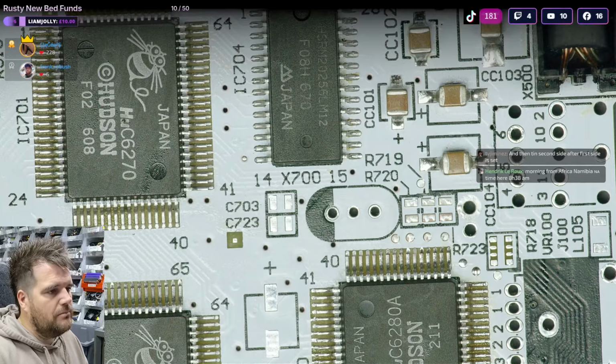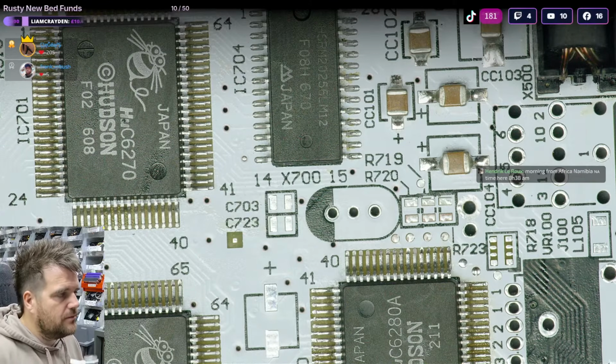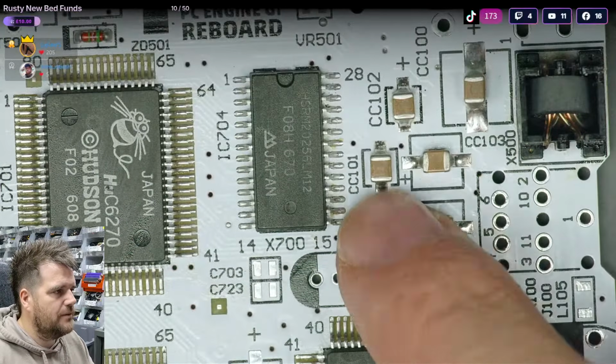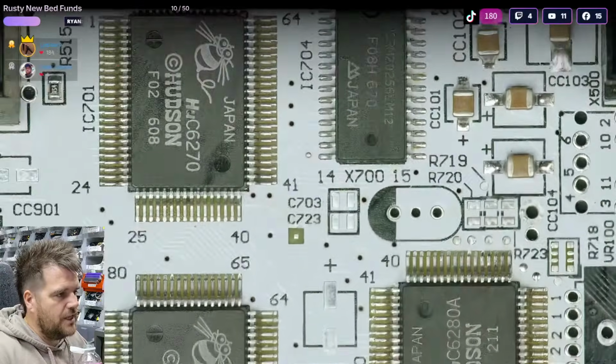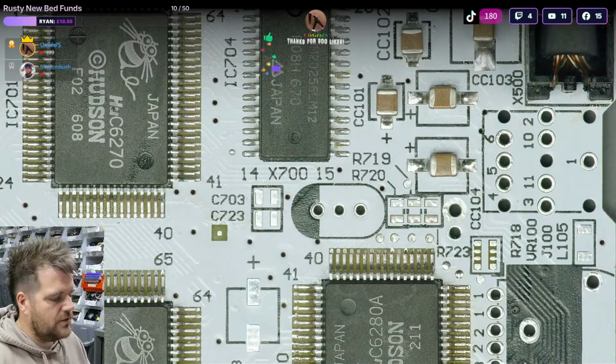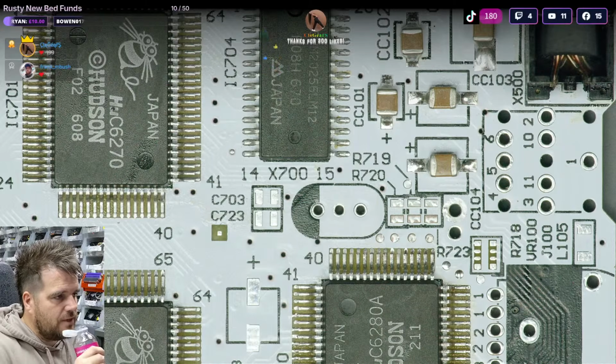The hot air will melt both sides evenly, let the flux and solder flow, and the component fly into position. So it's a much cleaner way of getting them to sit naturally. You saw all these pulled into position, and the fillets are perfect. You wouldn't do that with a soldering iron unless you're a lot more skilled, whereas with a hot air, you don't need to be that skilled to get that finish.